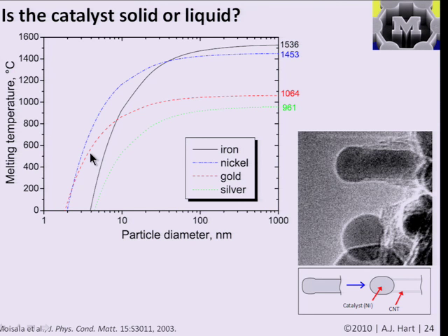You might remember the picture, the video I think we had on the first day, where this was an in situ TEM video of a carbon nanotube growing from a nickel particle. And we didn't talk about melting point suppression, but this was at about 500 C, and the metal particle was actually kind of inching along like a worm. It was changing shape. It was kind of squeezed out and then jumped forward. And it's not clear if this was entirely liquid at that state, but certainly it was compliant and could change its shape at about a temperature of 500 or 600 C.